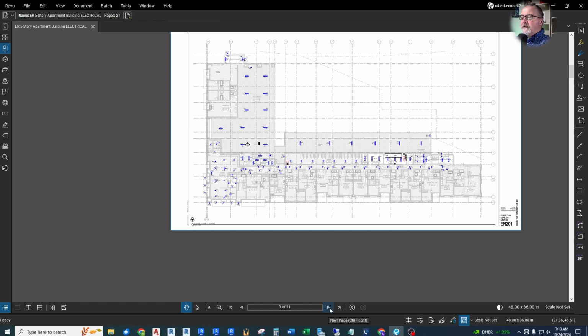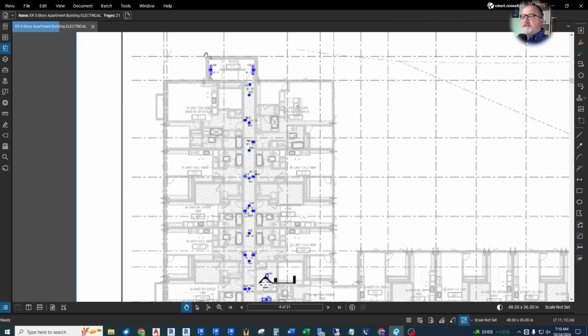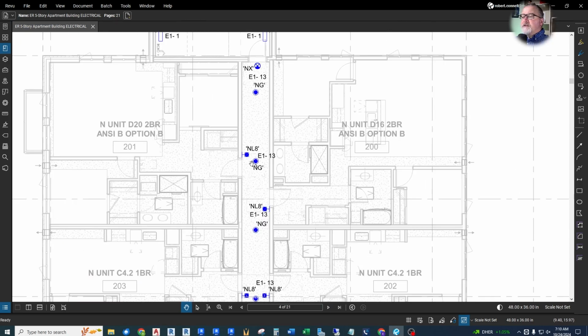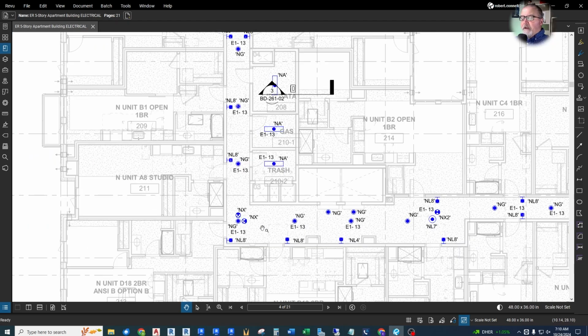And then similar for the next few levels, these are pretty much just corridors. Corridors and stairwells. Now these corridors are all darkened in fixtures. The entire corridor is emergency. Now as you get into lighting design, you realize that we may not need every light fixture on emergency to get enough foot candles, they call it, enough light. But a lot of times it's more economical to wire all of this to the same emergency panel, same circuits, to save some money. With LED, there's not a lot of power needed, so we can connect them to our generator without really increasing the size of our generator much because they're such low wattage fixtures.